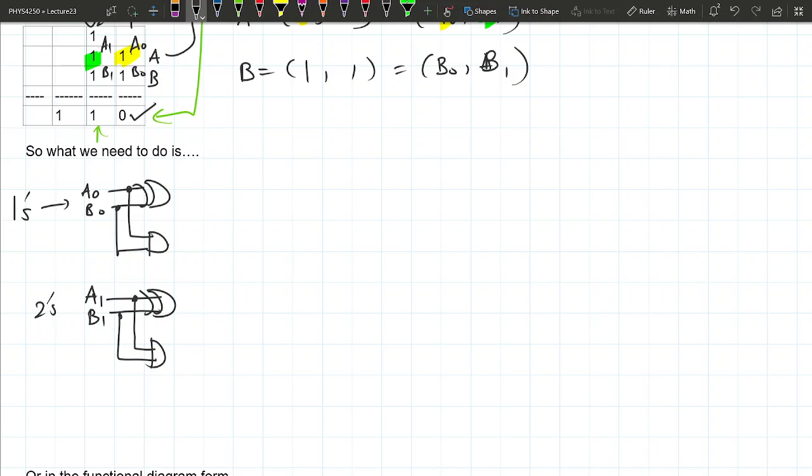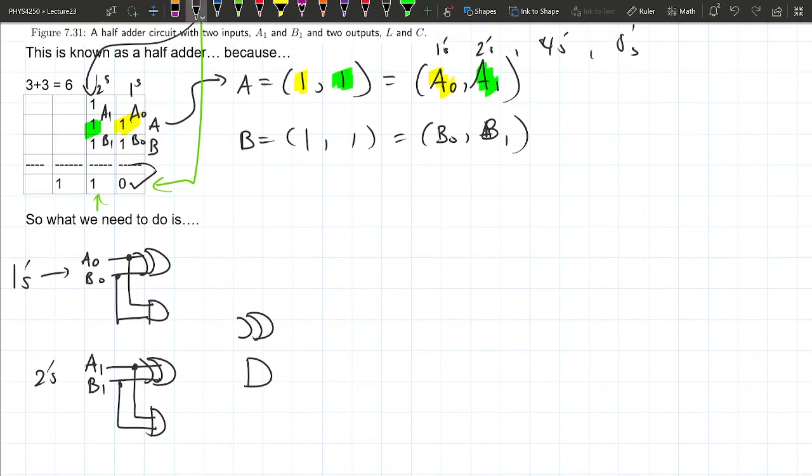And then as Matthew cheated and looked ahead, it's going to need one more. So to do 2 bits, you need not 4, but actually 3 half adders. So we're going to place another third one halfway between these guys. And I'm going to have to connect them together in a special way so that the places get placed correctly. So as we saw from this example up here,